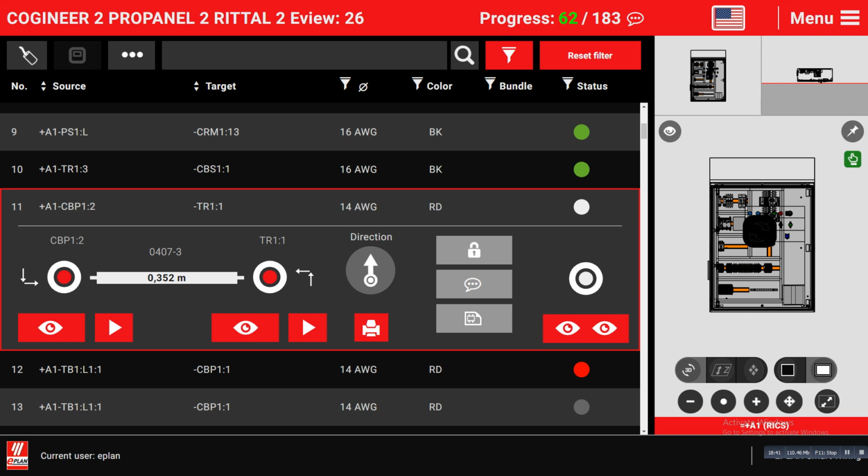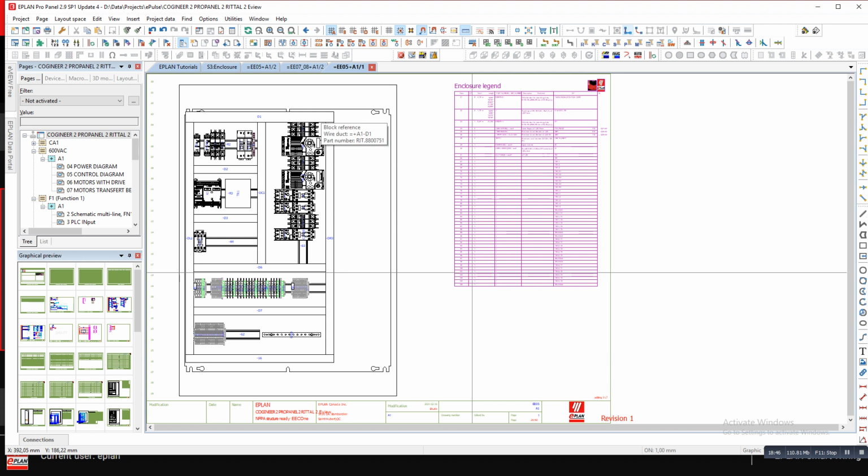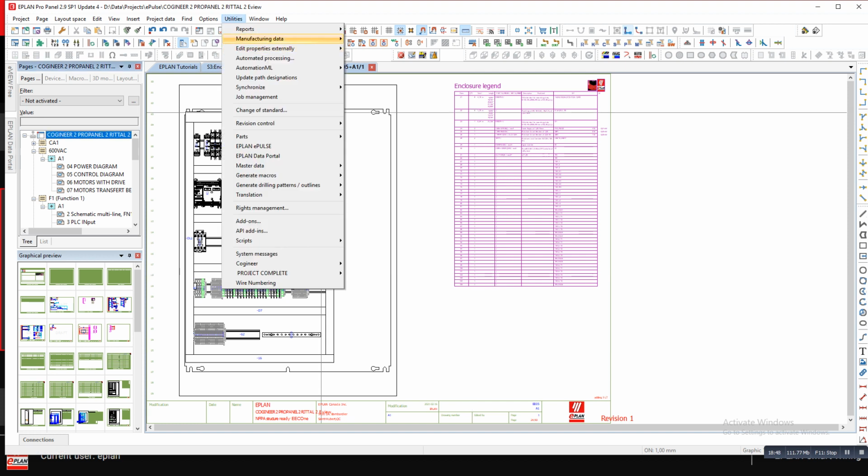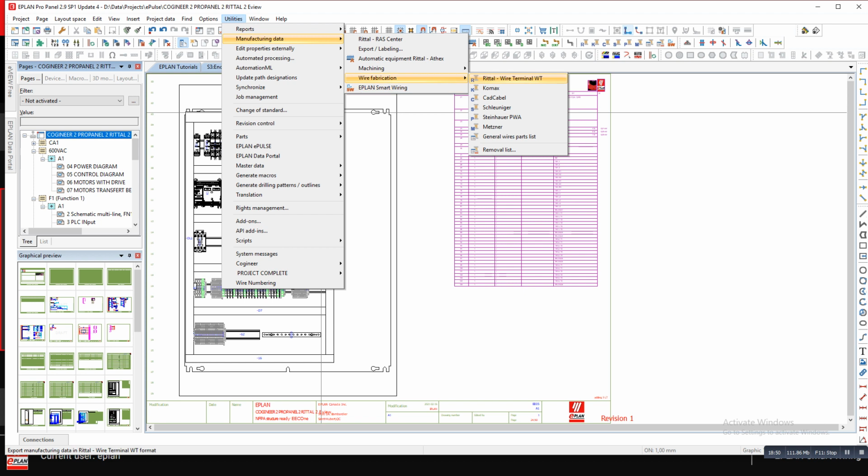So think about it. The wire fabrication tool that we offer here with the wire station will eliminate primarily the hand cutting of the wires and the hand crimping. So something that would take close to 3 minutes to do, right? Cut the wires, strip the insulation at both ends, put the crimp on, crimp the whole wire, and finally put the right label on there.